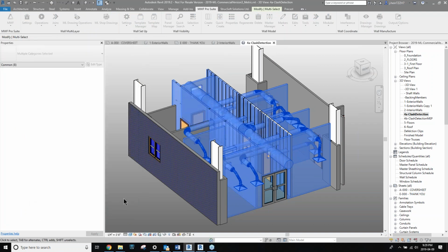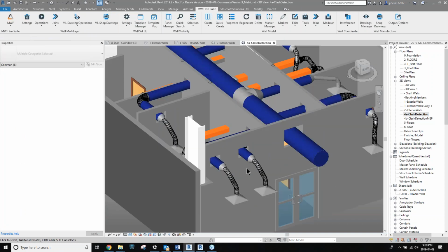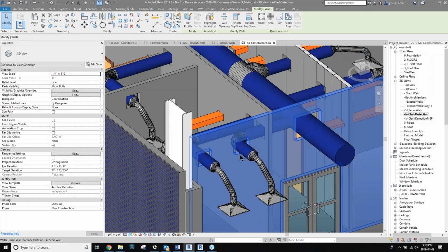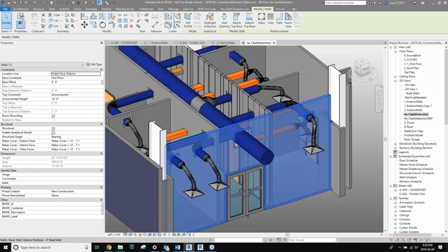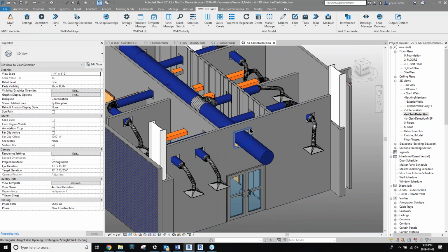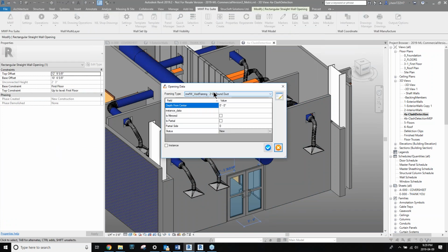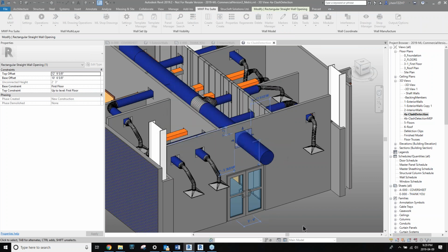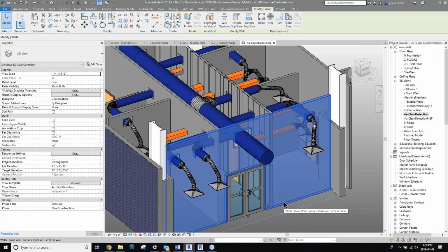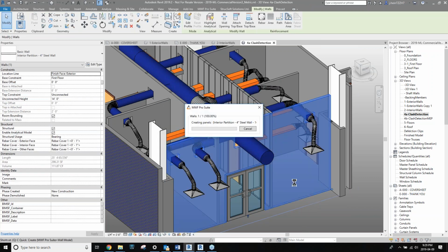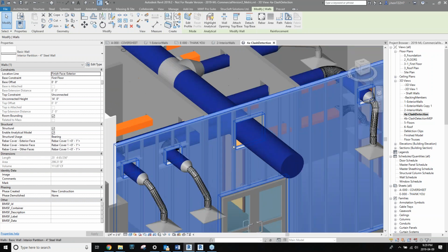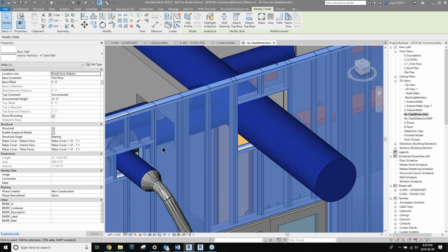It'll punch Revit wall openings in all my walls. So I have 3 openings here, another one there. These openings already get stamped with the marker. So if I look at apply opening type, you can see I already have a marker of framing. I can then just grab the wall, do my quick create, and it will frame around these according to that definition. And we'll zoom in on them and you can see. So there we have a nice simple one.